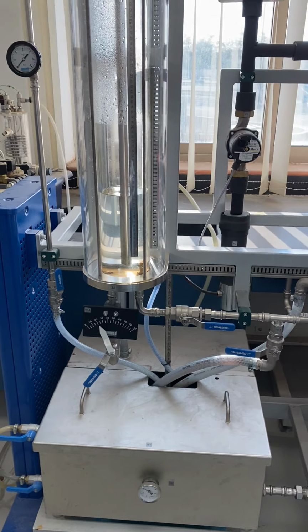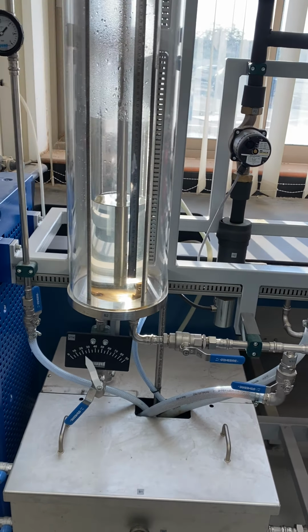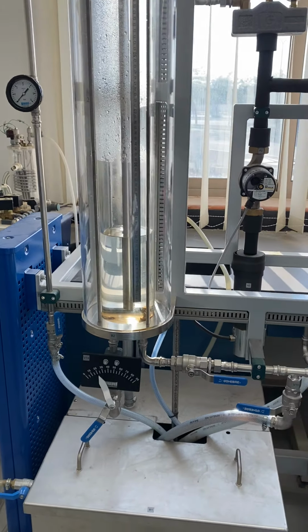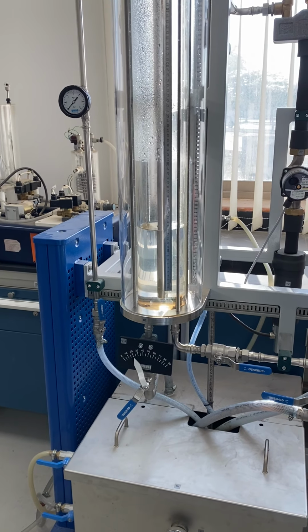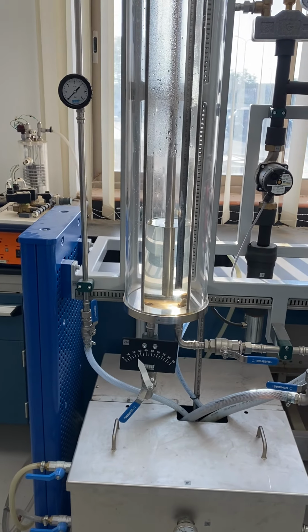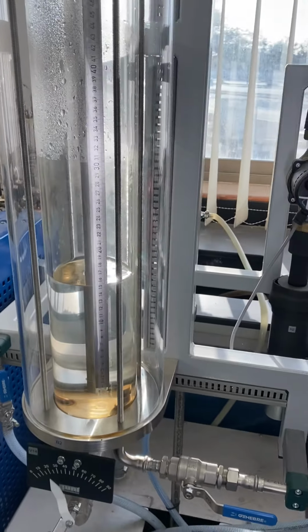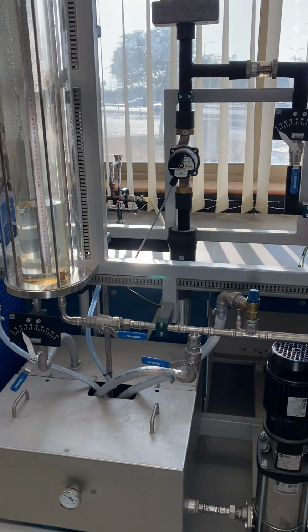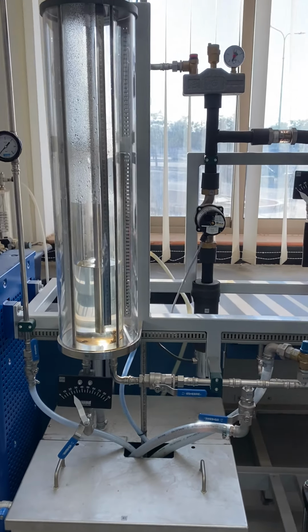Of course, in case, guys, both the inlet and the outlet flow rates are constant, and you observe that the sensor that measures liquid level inside the tank shows a change, then it is very likely that you might have a problem in your system. One of the problems is that you might have a leakage, or it could be a faulty sensor that does not give you the measurements correctly.